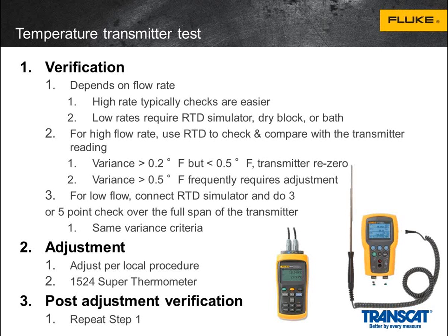Frequently what you're going to do is use something like a super thermometer, a very high accuracy thermometer, in order to do that adjustment. It tends to not be as common. Usually where you get into trouble is the differential pressure measurement. Last but not least, if you did the adjustment, you are going to have to go in and do a post-adjustment verification in order to make sure that you have done your adjustment correctly.